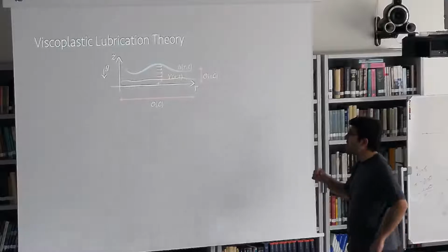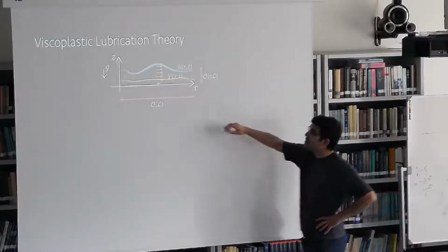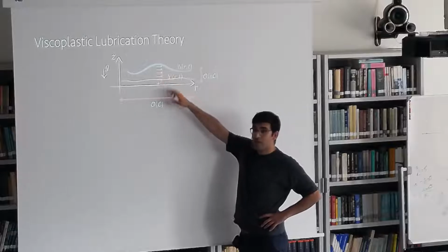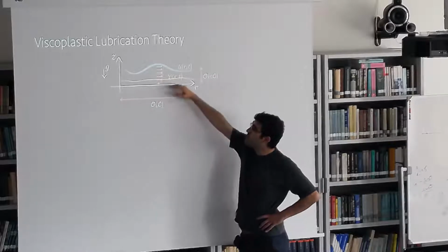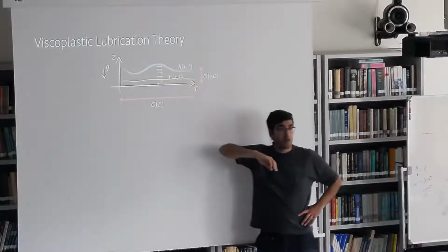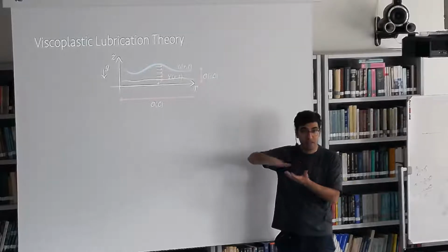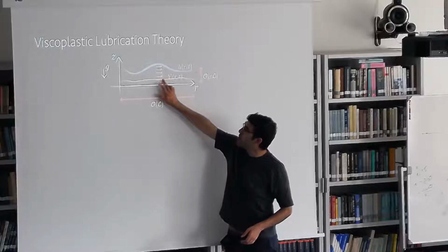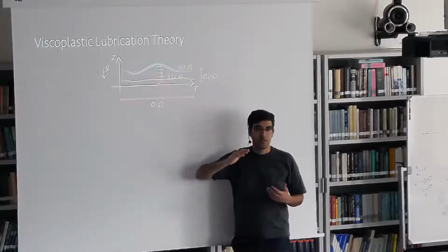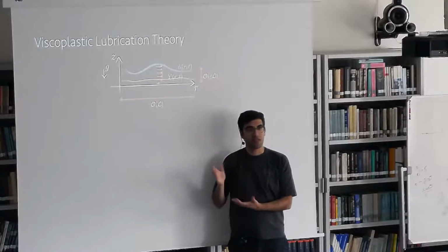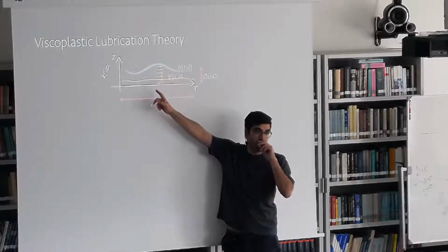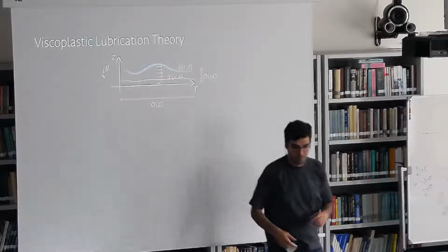Okay? And this equation has been known for Newtonian fluids for a very long time. What happens if you have a yield stress fluid is that at some point the stress inside your film becomes equal to the yield stress, meaning that above that stress, you can yield the fluid, so you can get deformation. So that's how the flow looks. But below the yield stress, you do not get deformation, and that's where you get this plug-like or pseudo-plug region on top. Similar things also happen in granular materials.